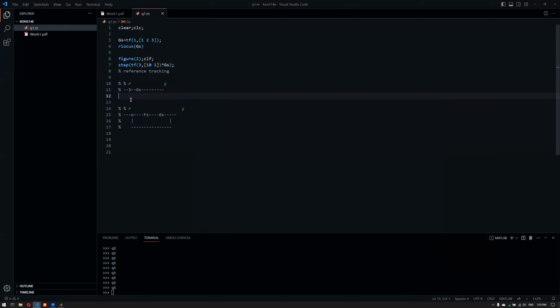Now, the open loop control strategy is mostly about just changing the gain, maybe adding a pole or two to have a certain behavior. The best way of designing a controller, of course, is to take the inverse if the system is invertible and if the inverse of the system is also stable. Then you might look for the control with the inverse of the system, an open loop strategy.